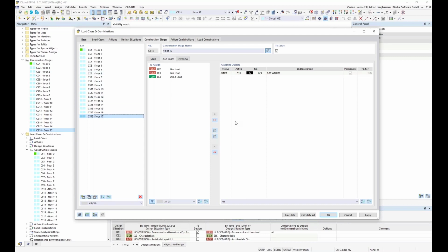In the last stage, when the building process is completed, I will apply the live load. The live load is non-permanent by default, because if I, for example, use it in an earlier stage, it is not considered in all following stages. You could also decide if a load is considered as permanent or not by clicking this check in the construction stage where it was first activated.